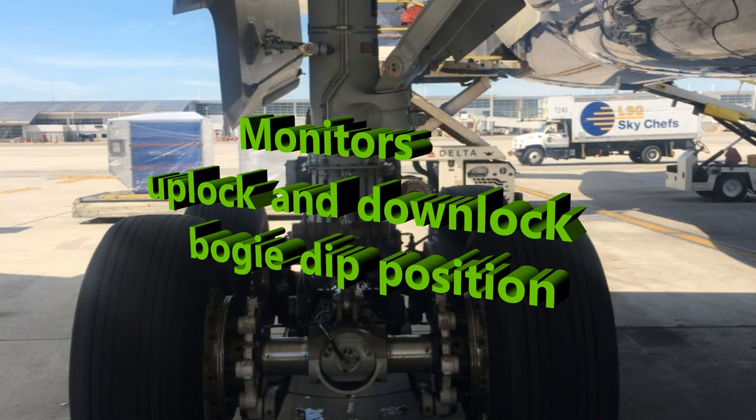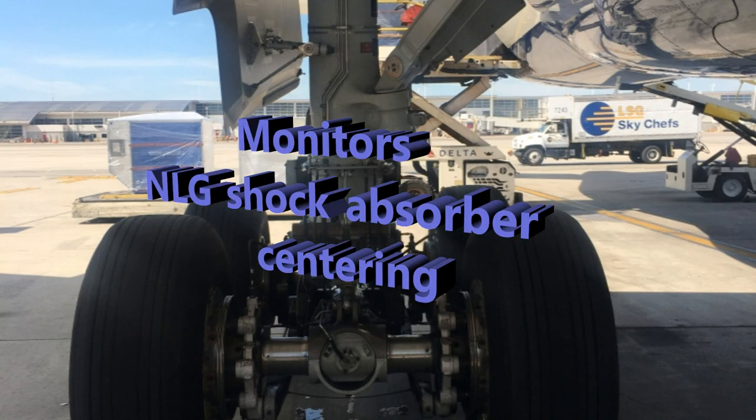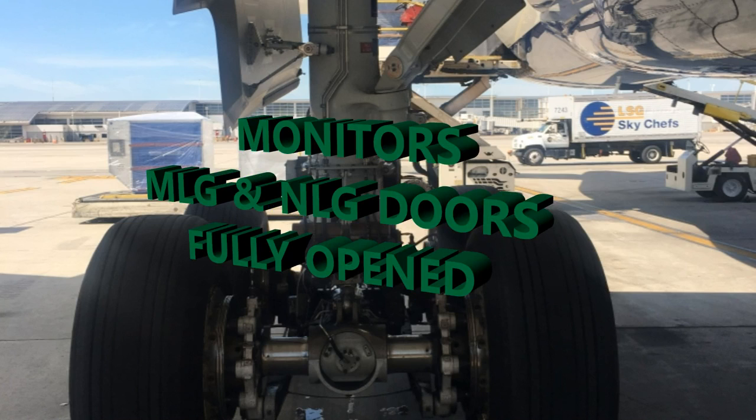You have the different monitoring of things for your main landing gear and your nose landing gear doors, up lock and down lock. You're also going to have monitoring of the bogey, your dip position on the bogey, and then the nose landing gear shock absorber that's going to be extended and centered. It's going to monitor that. Also your main landing gear and nose landing gear doors fully opened, and also the shock absorber for the main landing gear. So both shock absorbers, main landing gear, nose landing gear, and then your main landing gear and nose landing gear doors fully opened.